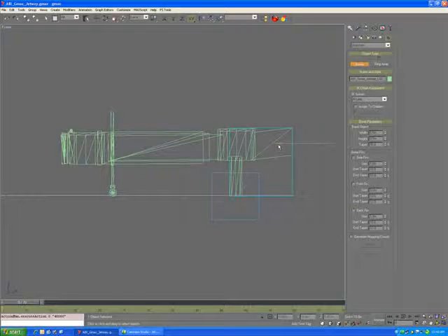The side view seems to work the best. Bones have standard orientation anyways, but the side view seems to be the best for drawing them. As you see, as you hover over it will lock to the pivot. So I'll start with the root node back here, go to this next node here, and then the next one, and to the next one, and not the leg, but to the final one out there. And actually, I am going to create one last bone right there, because you need an extra bone there to rotate the sort of mouth of the Jetway. Okay, so that's my basic bone structure for the main linkage of the Jetway.